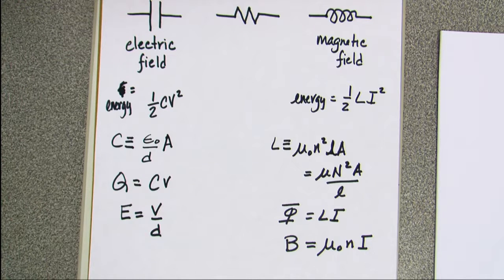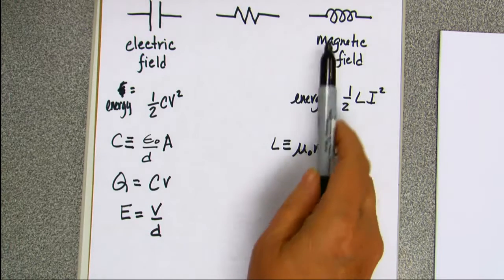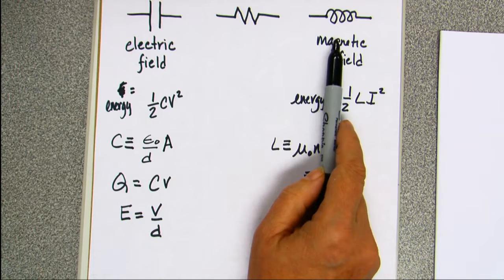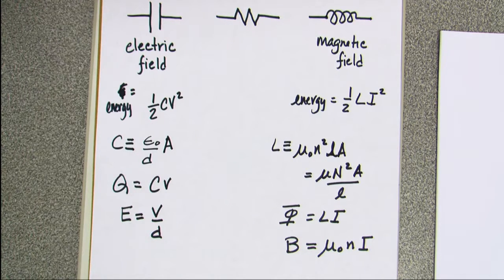And the negative sign that we end up with, the back EMF, indicates that the voltage is always opposing the current. Okay? This is going to have voltage opposing the current. So when we end up redoing Kirchhoff's rules and we're throwing in an inductor, we have to remember that our inductor tends to fight the current.